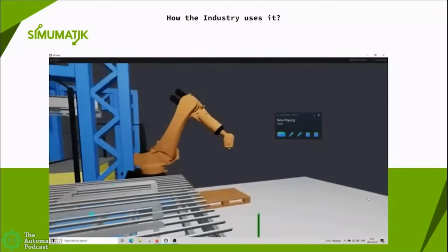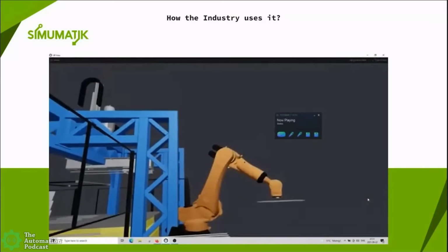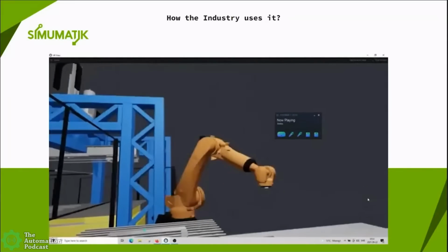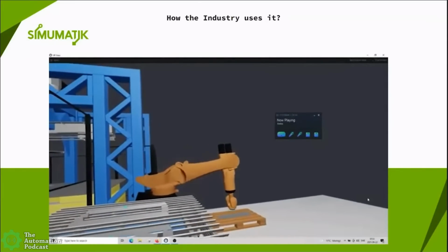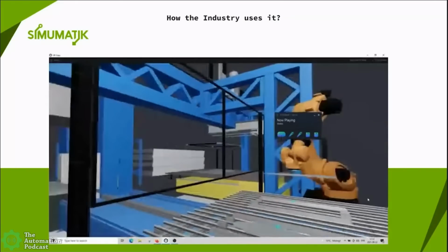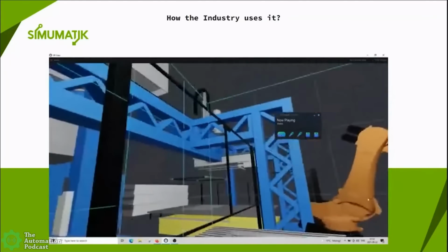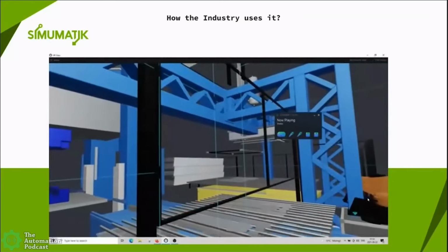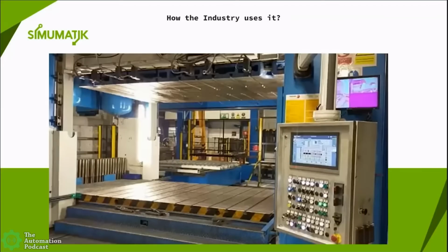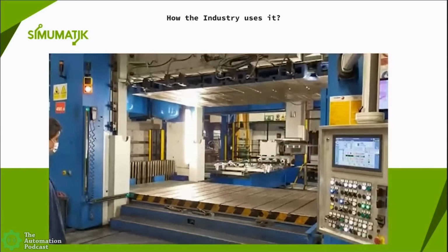Now the next question is, you said you actually then tied this to a real PLC or a PLC sim? Yes. This isn't some script inside your software. This is actually getting live values from a PLC. Exactly, exactly. So this is not an animation. What you basically build is a model of the hardware in your system, all the mechatronics, all the sensors. And what happens is that the model connects to your PLC, and it's going to read and write in the memory, so you can execute your PLC code as in the real system.